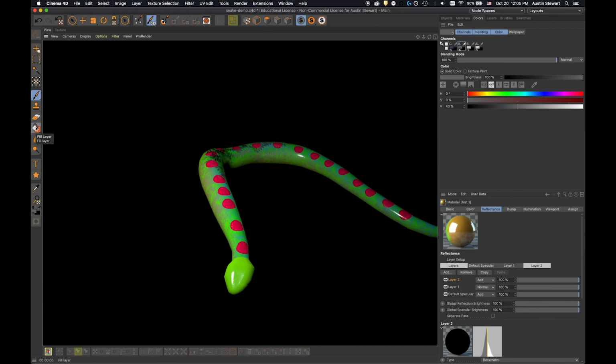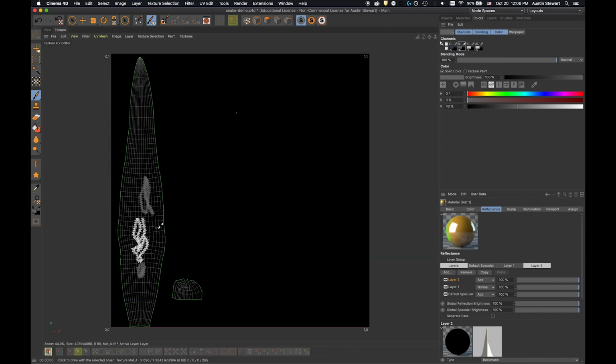The only thing that works a little differently is the fill layer or fill bitmap, but the gradient tool works pretty similarly. And there are selection tools as well, like magic wand and rectangle selection. Most of the time for the rectangle selection, you probably want to be in texture view to be doing those types of selections. All right, and that is what I've got. So hopefully this is a really useful tutorial that shows you how to work with body paint.